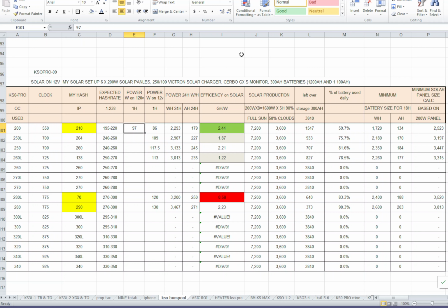So you could get that emergency power if you didn't have enough solar collected through the day. But we're going to calculate based on 90% efficiency on the solar panels and 90% efficiency on the battery. Actually, the battery is rated for 95%, but we'll be very conservative, because when I ran this system for a week, I had quite a few shutdowns because of that.